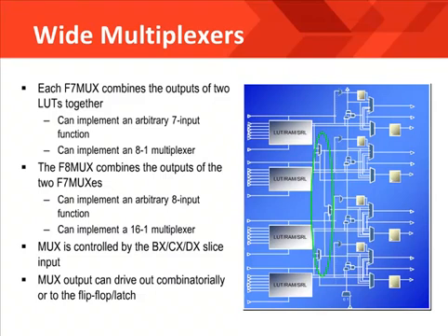The reason that these multiplexers improve the speed of the design is because there is dedicated routing between the multiplexers that is low fan-out and fixed between the logic resources. It is also fast because the dedicated multiplexers are faster than building the equivalent logic just with LUTs. What is most important to remember is that each of the dedicated resources has an intended purpose of saving LUTs and improving the speed of your design. Also be aware that if you are going to code for a large multiplexer, you code with a case statement in your HDL. This is required for inference of the dedicated hardware mux.